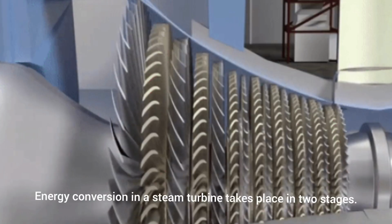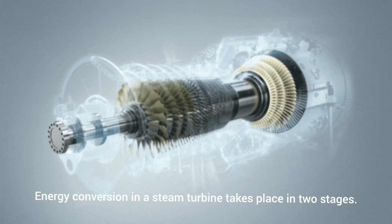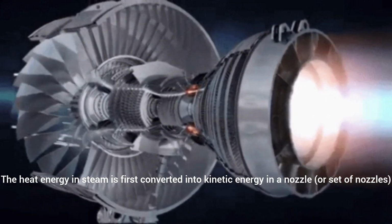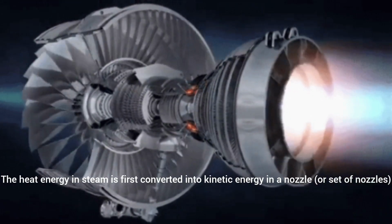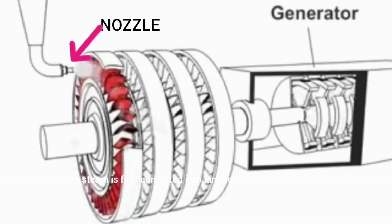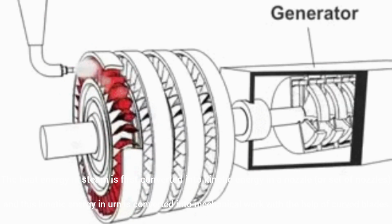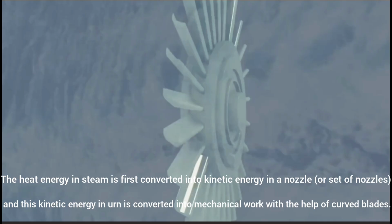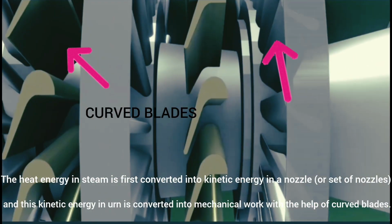Working principle of a steam turbine. Energy conversion in a steam turbine takes place in two stages. The heat energy in steam is first converted into kinetic energy in a nozzle or set of nozzles, and this kinetic energy in turn is converted into mechanical work with the help of curved blades.